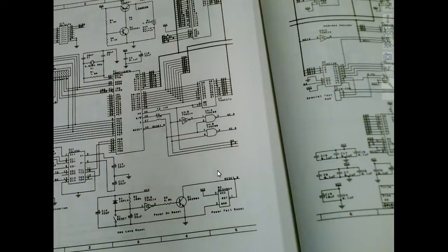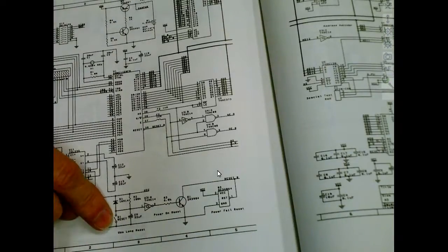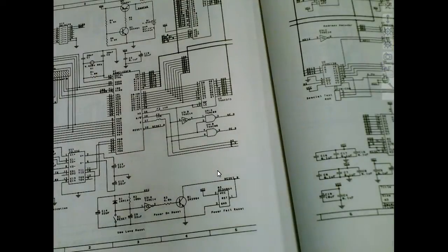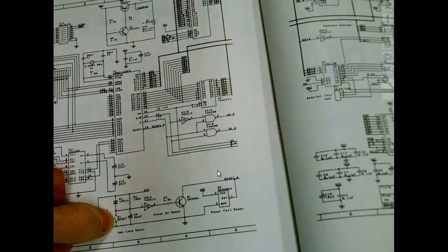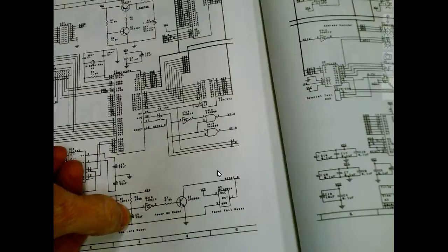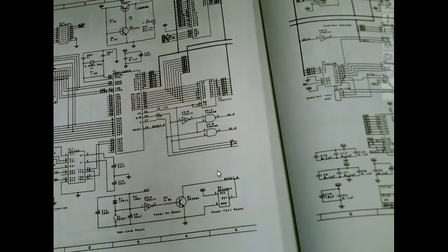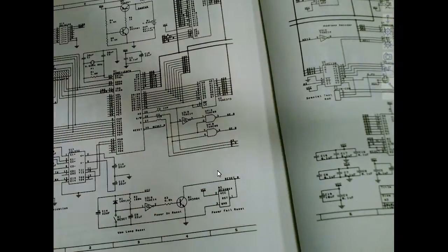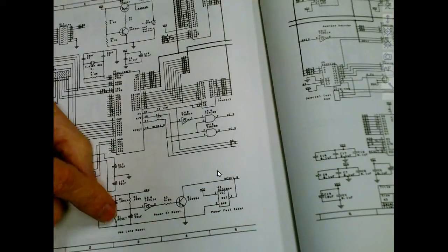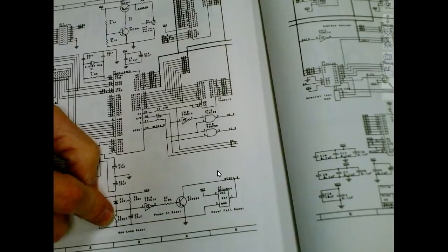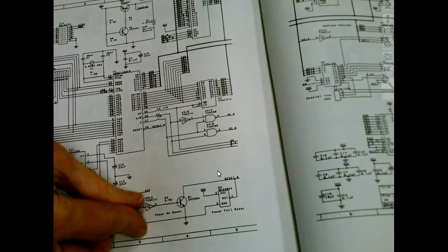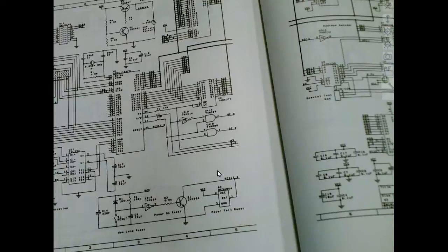These guys have a reset button. If you open up these doors and look, there's a reset button on desktops. Desktops usually have a reset button. Well, there's the button right there. When I press that button, it discharges the capacitor. And then when I let it go, it lets the capacitor start charging. And as soon as it hits the threshold, it generates a reset. So this would be you resetting the computer. And then, of course, if you turn it on, and the power supply comes up, it does an automatic reset.